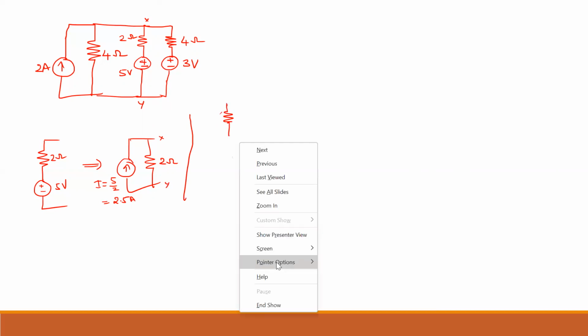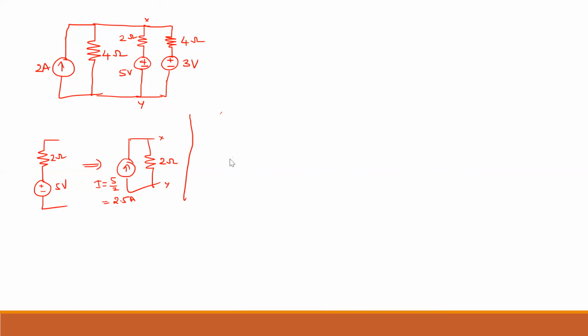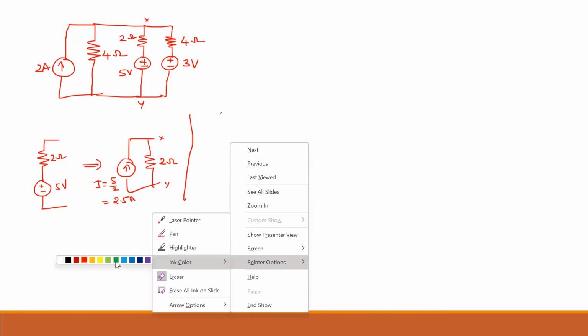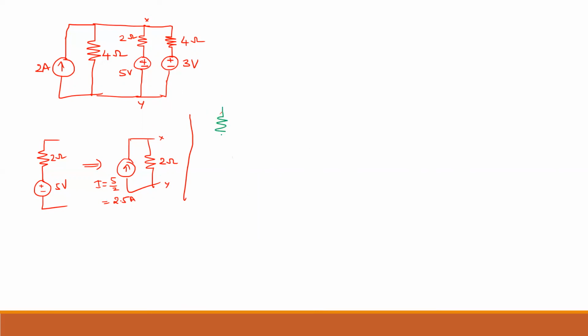One I can do. So anyway, this is X and Y. One more branch is also there. What is that? 4 ohm and 3 volt. Same thing. 4 ohm and 3 volt also connected, right? So that also we will simplify. Now again I will simplify here. The direction of the current always represents the positive terminal wherever it is, the direction is like this, right? So generally for sources the current will flow from negative to positive terminal.